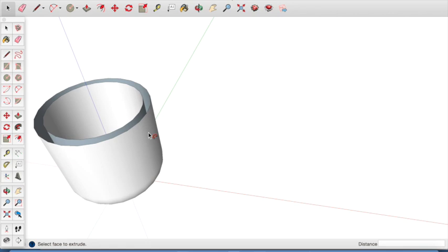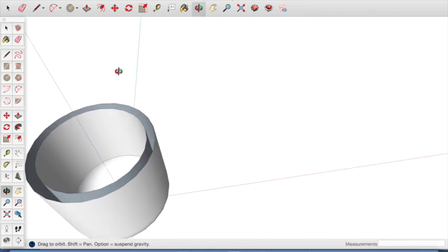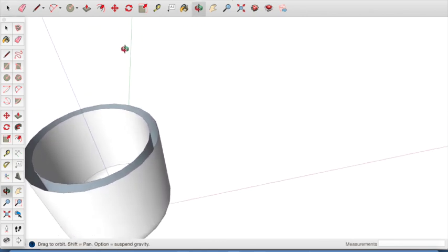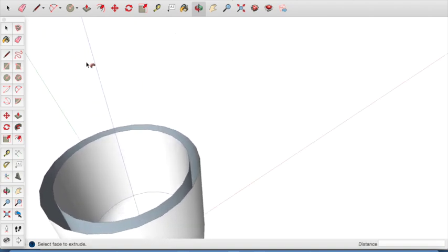We now have a coffee cup, but without the top sections filled in with a solid surface. To do this, rotate the coffee cup so you can see the top. Take the line tool, click the line tool and draw a line from end point to end point.